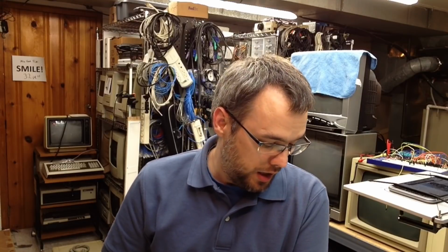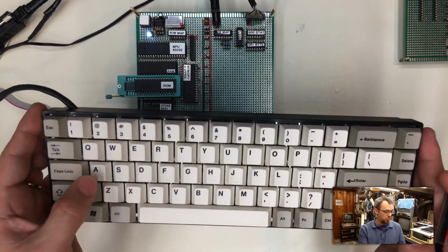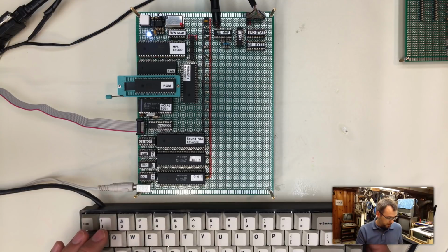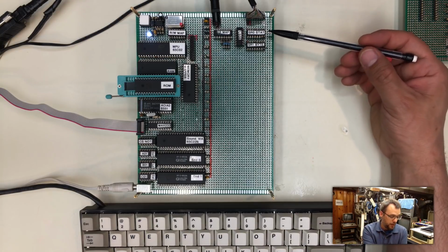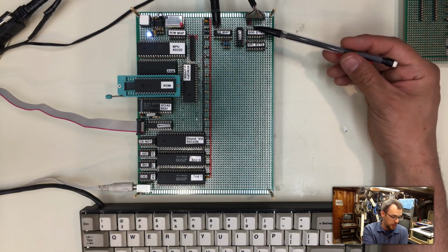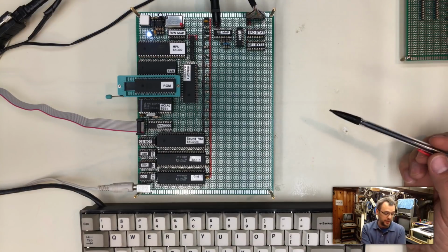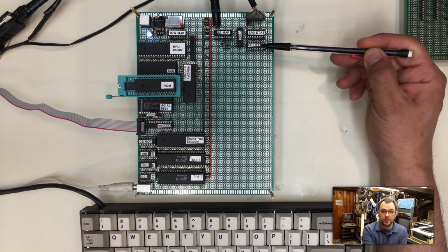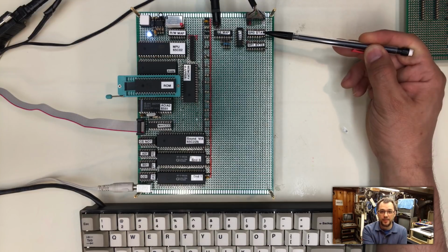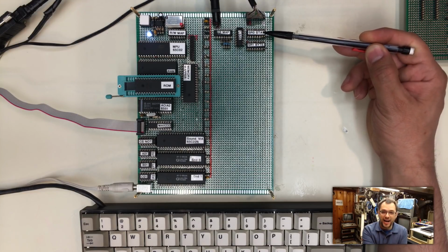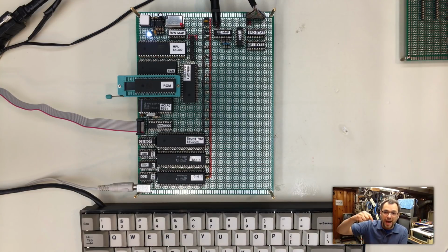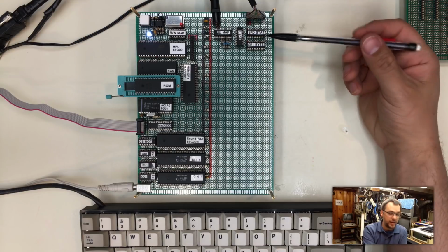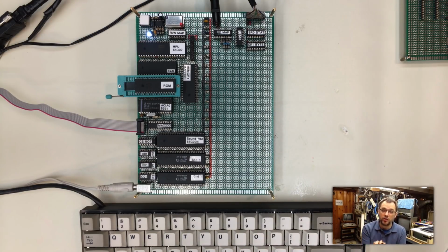But basically, what was happening is, if I would type a key on the keyboard, my code would fetch the byte from the byte value, put it in the accumulator, then clear the register to clear both of these simultaneously, which would result in the byte value becoming 0. But this would still have the status set to "I have a key waiting." So this would loop through several times as if you were smacking the key super fast. And it would read a whole bunch of zeros after reading the first character I actually typed, and it would stuff the buffer with a whole bunch of junk.